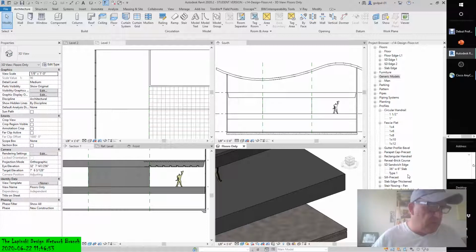Another floor is modeled with a negative offset value to accommodate the thickness of the tile material. And the tile has been placed as a unique floor element. Now, there are various ways to do this. If you do not need a finish, but just a slab depression, you can create it with an in-place void extrusion.